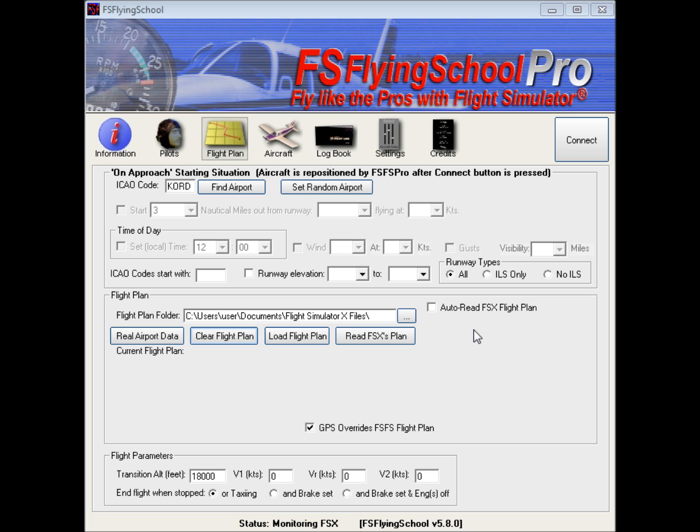So what this means is that if you're going to be using a flight plan, the recommended sequence is that you would start FSX, you would get yourself into an airplane, sitting at the controls inside the cockpit as it were, and then in FSX you would load a flight plan. As I'll repeat here, you will be doing this in FSX.